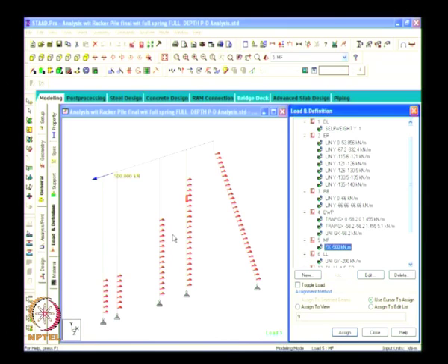So when the ship is tied here, there will be a mooring force. The mooring force is about 1500 kilonewton, but that 1500 kilonewton will be distributed for 3 panels. Each panel is 4 meter, so 3 panels is 12 meters. The bollard spacing is 20 meters. So suppose I am pulling from this center point of the table, it will not go only in the panel here, it will distribute to adjacent panels also.